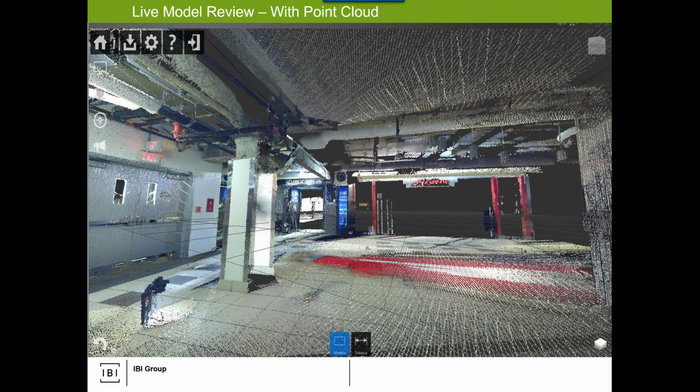The other example is when we're using point clouds to validate as we're constructing. I think I talked about this last week. In the civil world, you take some boreholes that may be 10 meters apart, and we make some grand assumptions that the things are flowing from borehole to borehole. Once we remove the street and start construction and you expose what's underground, who knows what you'll find in between those boreholes. Point clouds are often used to take the scan and do a comparison back to the models to ensure that the design intent and clashes, everything, are in order.